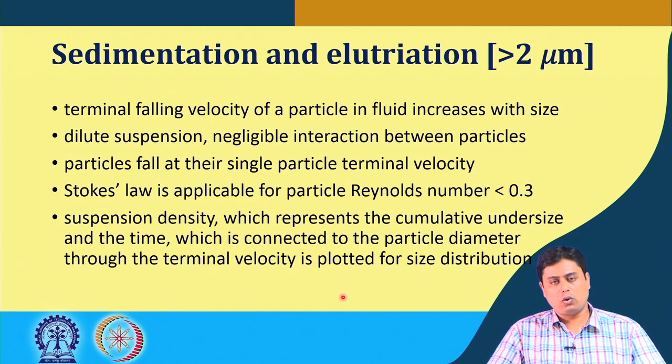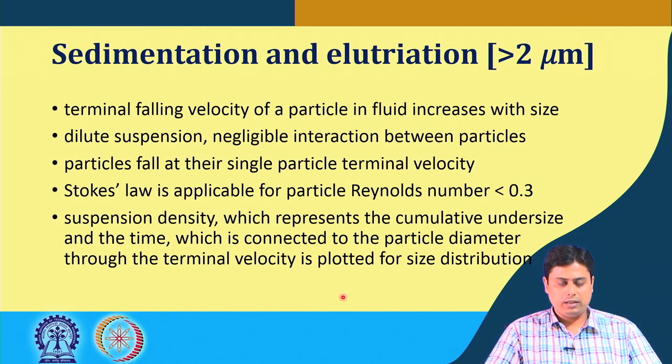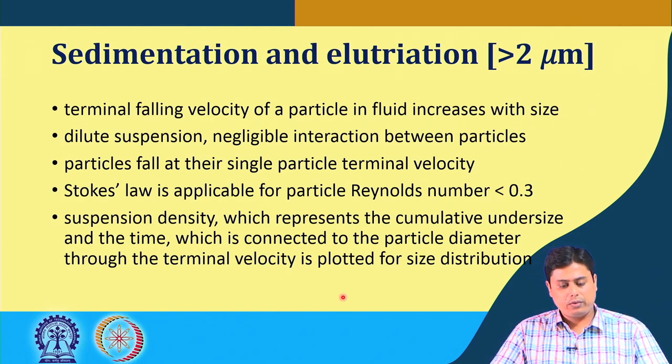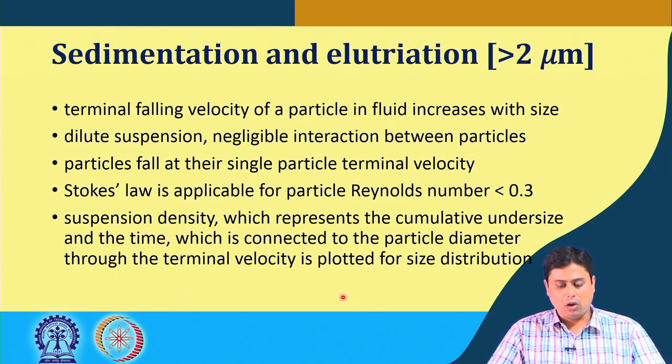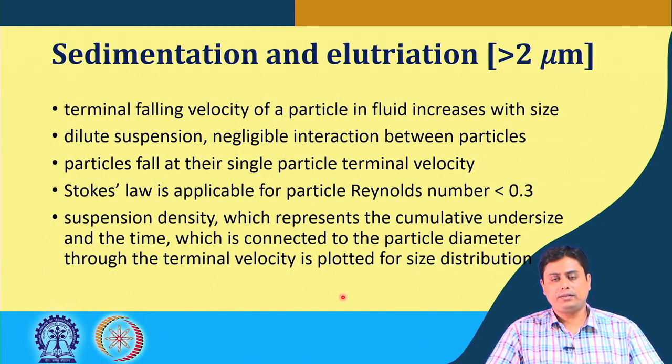If you remember Stokes' law, this is, as I mentioned, prerequisite fluid mechanics knowledge that you need to have for this course. You would understand that this terminal falling velocity is essentially dependent on the particle size. In this technique, based on that fact, we typically apply Stokes' law, which is applicable for a particle Reynolds number of less than 0.3.